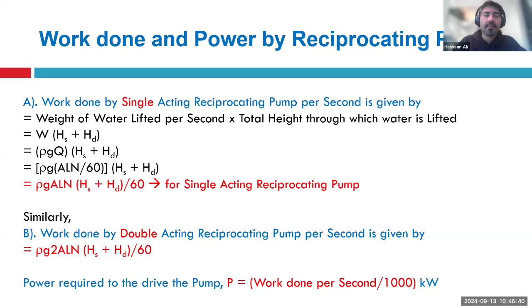The reason is that your prime mover, which is a diesel engine, is usually an off-the-shelf component or assembly. So you will have engines driven at particular RPM, and you really can't change that much. Then you need to check in the catalog what types of gear reducers are available, so you can play with that in your equation.